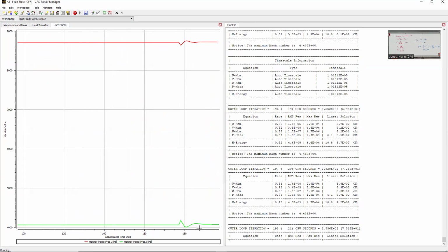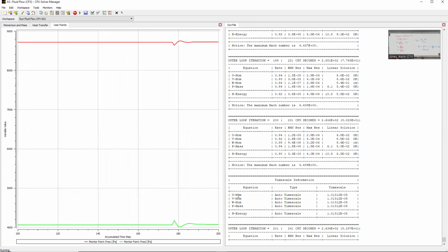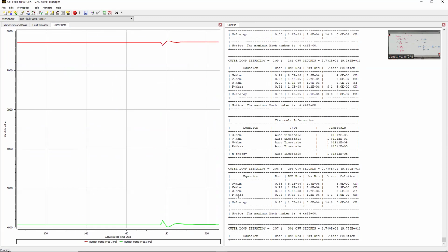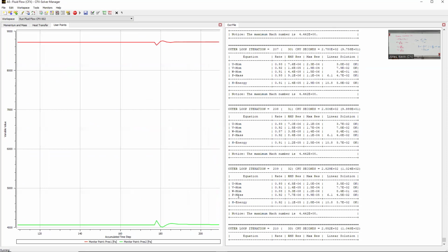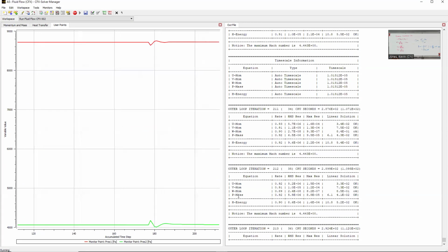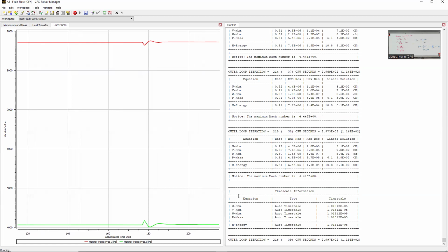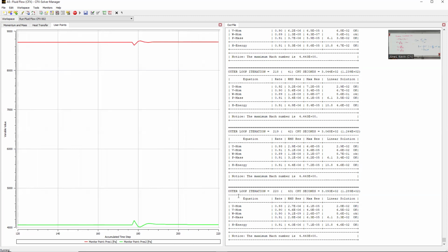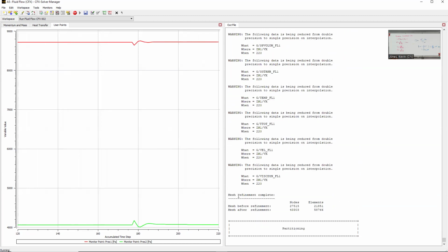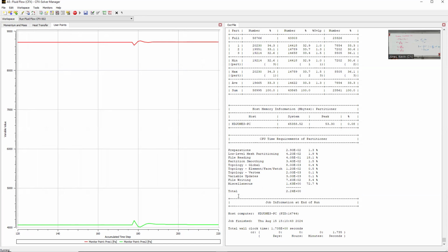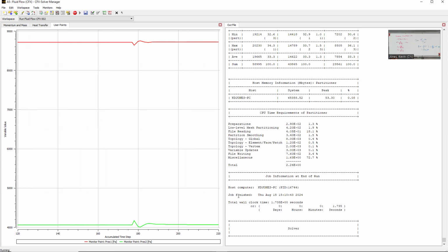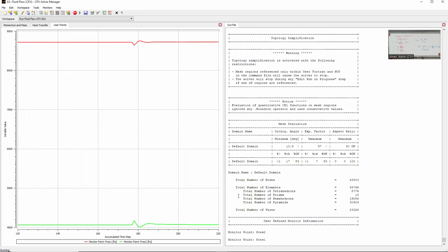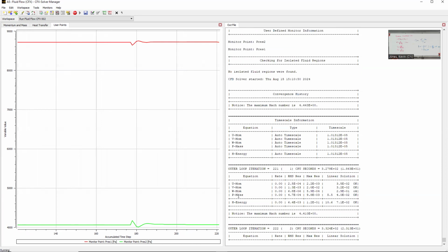Disturbance, yeah. Too many cells in the third direction, because it doesn't honor sweep where it remeshes. What it tries to do is if it makes the cells small in the XY direction, then it's going to also try to make them equally small in the Z direction. I've tried to make the sliver of the domain tiny, but it doesn't actually end up giving you better results. One is the cells are all smaller, so the DT gets smaller. And I can't seem to get it to converge as well as I get with the 1 millimeter thick domain.